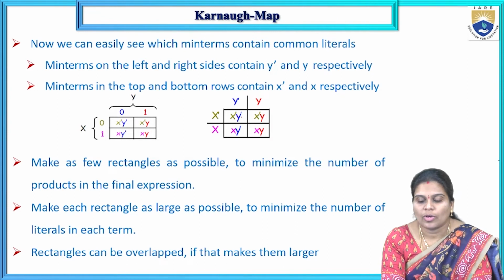If you include this first box, we can form this one group or this one group. Similarly, with this box, we can form this group or this group. We cannot form a group in diagonal square boxes. We only form groups in adjacent square boxes, not in the diagonal form.